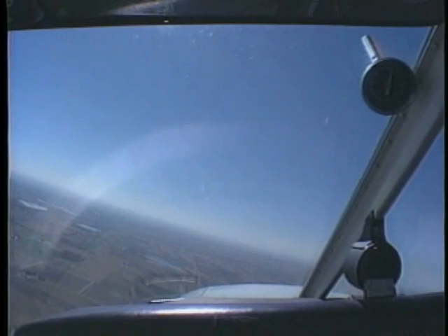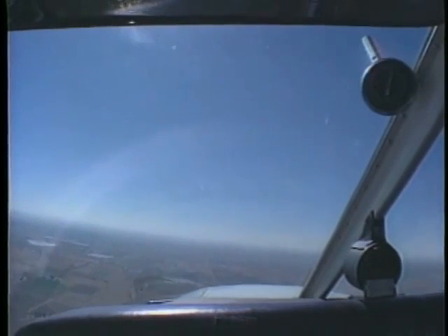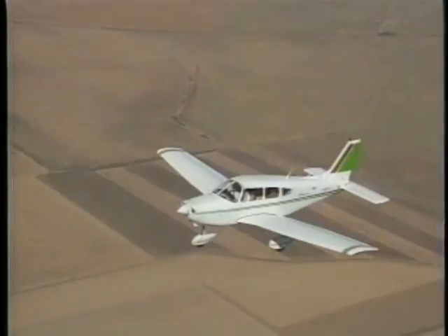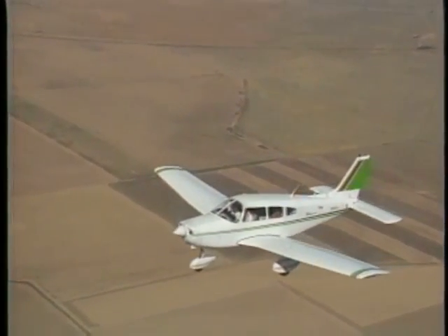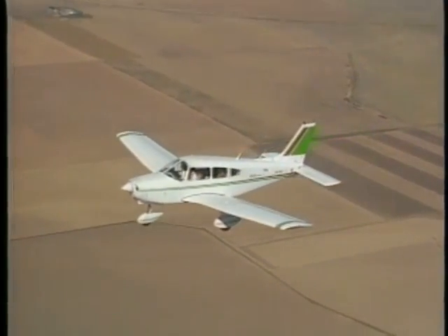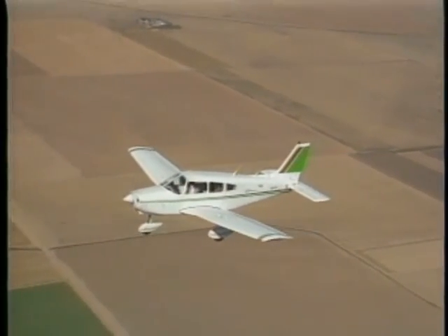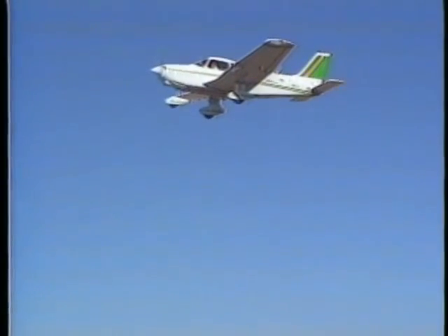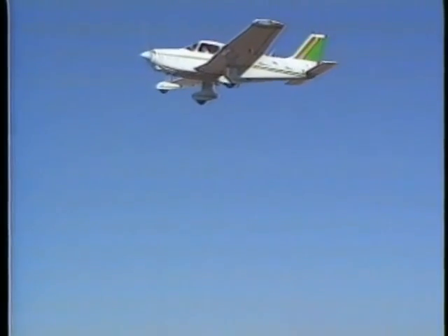With all of this in mind, let's look at the planning and coordination needed to fly 8s on pylons. After clearing for traffic, start by determining the wind direction, and then select 2 pylons that are in an open area free of hills and obstructions. They should be spread far enough apart to permit a few seconds of straight and level flight as you fly between them. The pylons should be aligned perpendicular to the wind, and at approximately the same elevation to make altitude adjustments easier to accomplish.